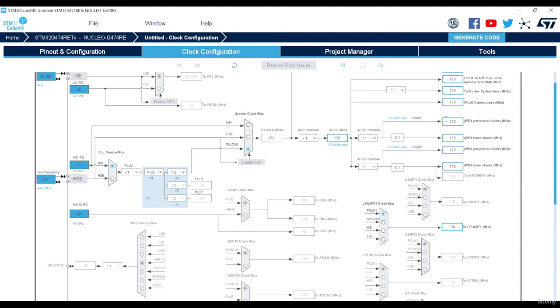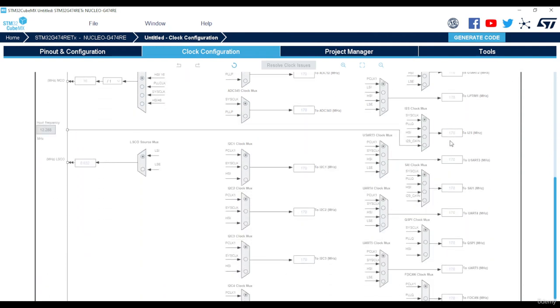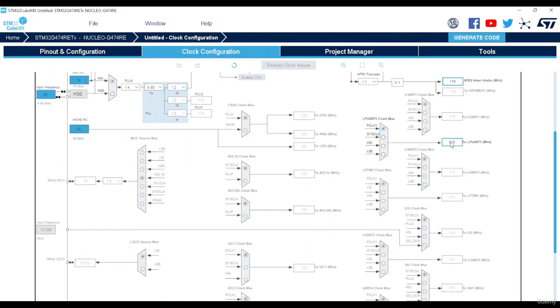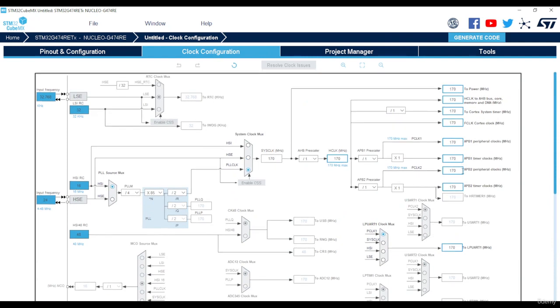Okay, so for this particular board that I'm utilizing, the maximum clock frequency is of course 170 megahertz. Of course, you can adjust it here. You can put some prescalers over there to reduce the clock speed. But in this case, I want maximum PWM resolution to realize closed loop control. It's easier that way. I have more resolution in the voltage that I can select. The resolution is finer. So I'd rather just have it at the maximum clock frequency. So this is just perfect.